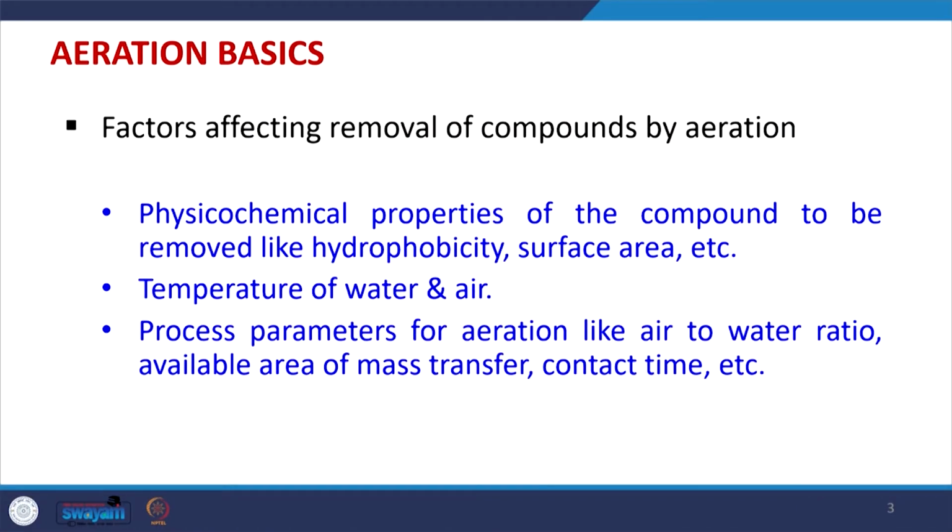Similarly, there are a lot of process parameters which have to be designed properly in the aerator, like the air to water ratio, that is, the amount of air that we are using with respect to water. That becomes very important. Also the available area of mass transfer, which we are going to study in detail, as well as the contact time, because it may require a certain amount of contact time before the gases actually come out of the interface and go into the atmosphere.